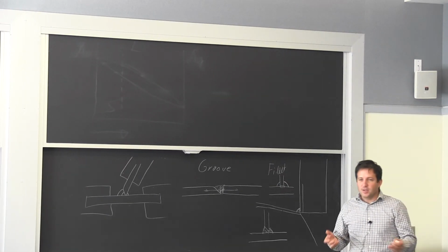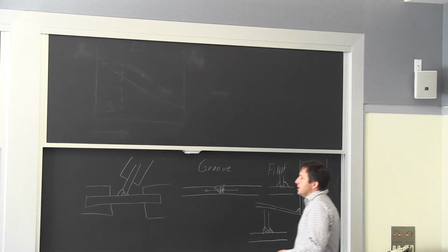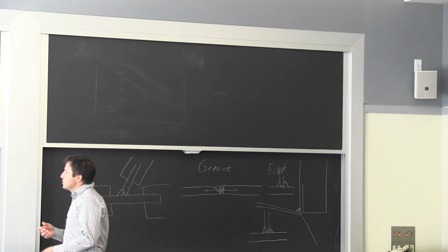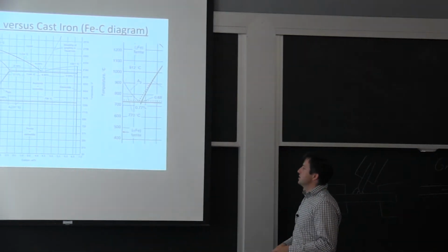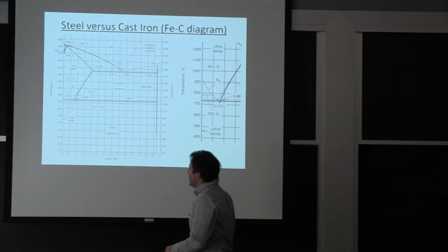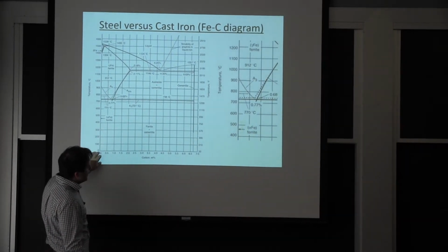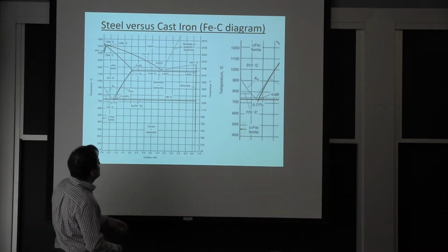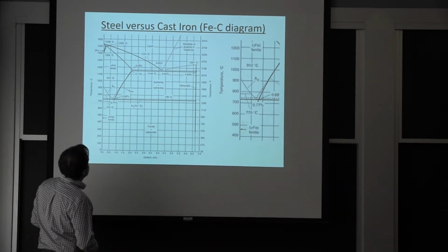It's kind of an old technology. It's been around for a long time, yet it's still used quite a bit. And you get it a lot from Professor Eger's class in terms of how much volume of steel we use and different kinds of steel. So we're showing the diagram here, probably for the last time, where we go all the way from 0 to 6% carbon, and we have the cementite here at 6.7%.